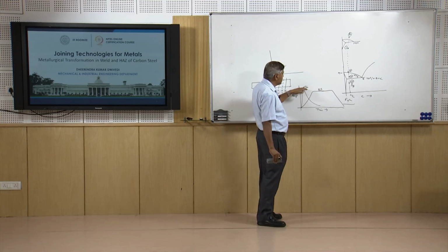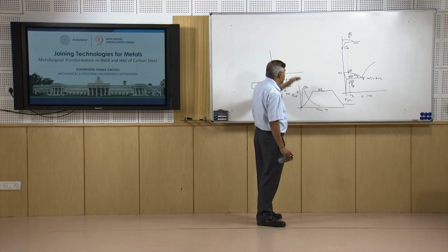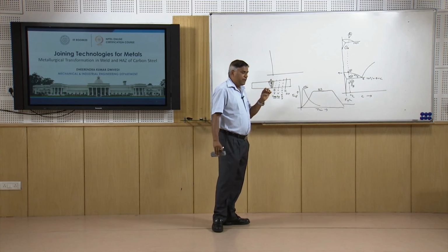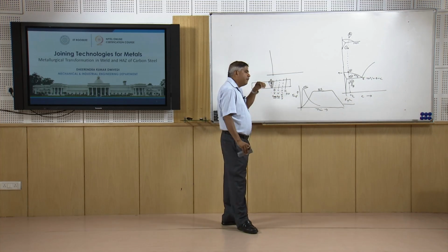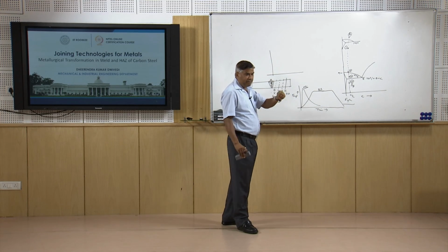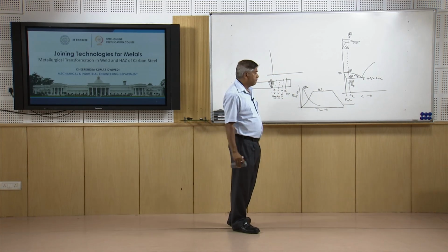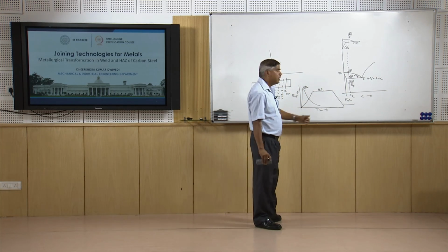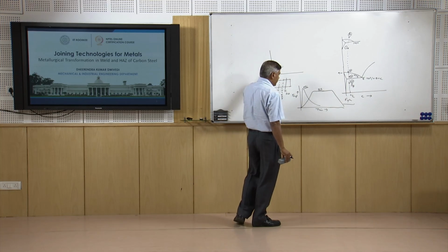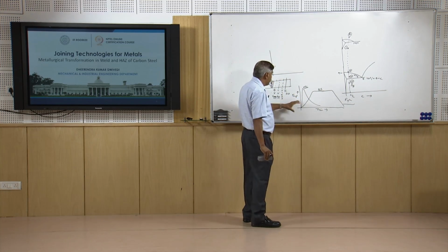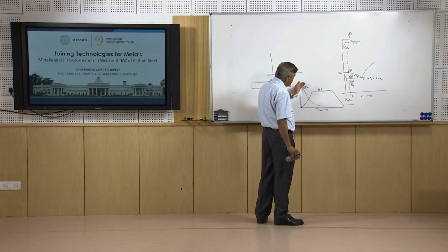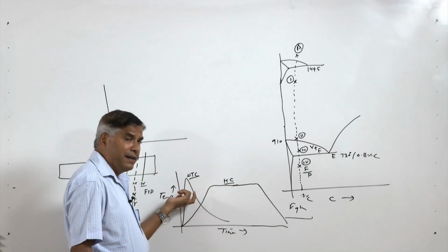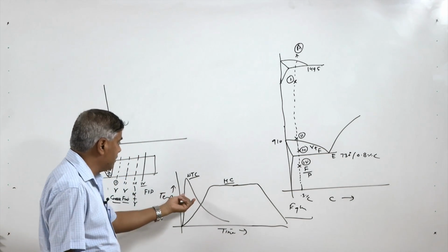So the temperature here reaches even up to the fusion temperature and above, but the heat treatment is carried out normally in the austenitic temperature band, which is say 50, 60 or 100 degrees centigrade above the upper critical temperature limit. So that is about 900, 950 or maximum 1000 degrees centigrade, not like 1400 or 1300 degrees centigrade. But the temperature experienced is much higher, and the rates of heating and cooling experienced are much higher, but the time of retention at high temperature is limited in the case of the weld thermal cycle.